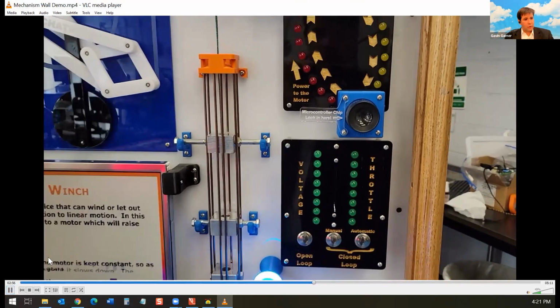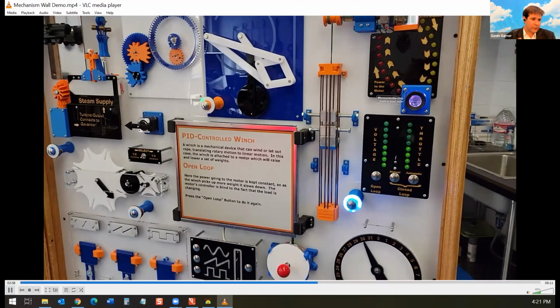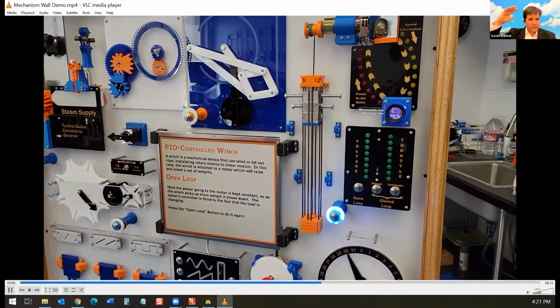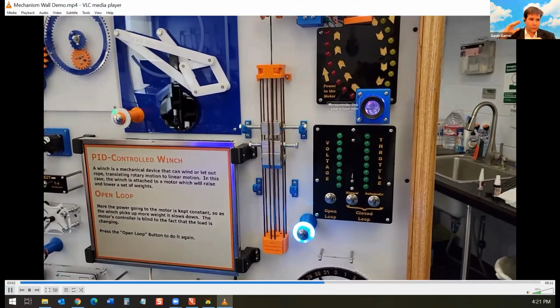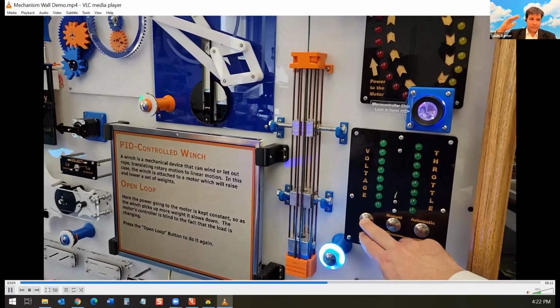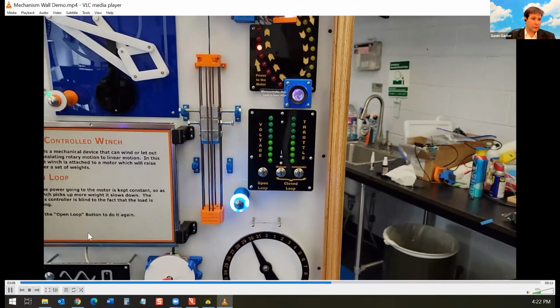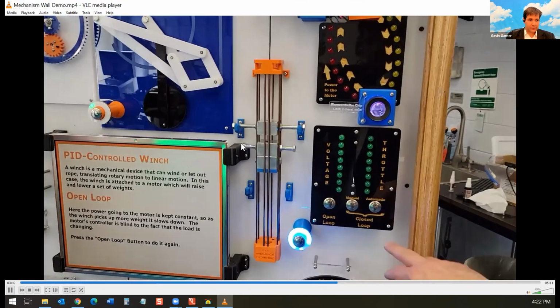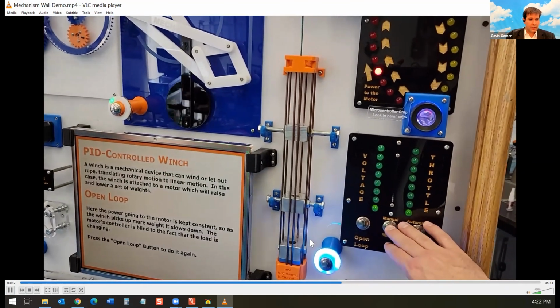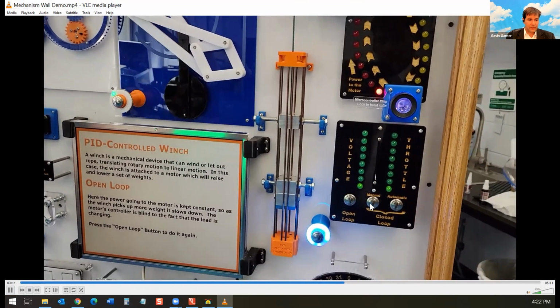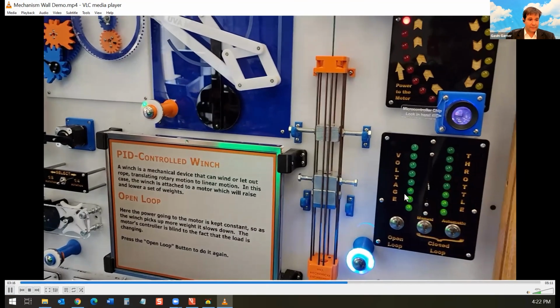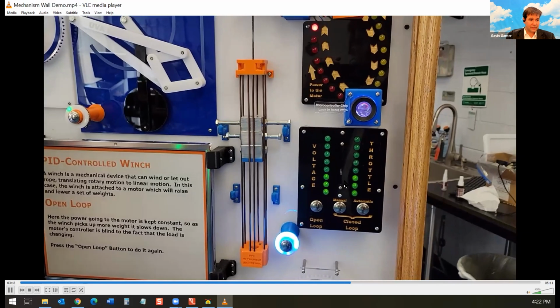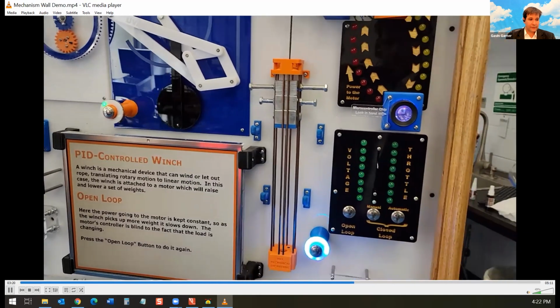All right, this is more of the modern mechanical brain in action. I'm showing a demonstration of a winch lifting up weights. Let's say you wanted the winch to lift the weights at the same speed, regardless of how much weight it's picking up. If you do it in an open loop, the more weight it picks up, the slower it goes as the motor gets bogged down. So what you could do in a manual mode is be the feedback loop, and give the motor more gas, more power, as it picks up more weight. It's slowing down, so I'm giving it more gas.